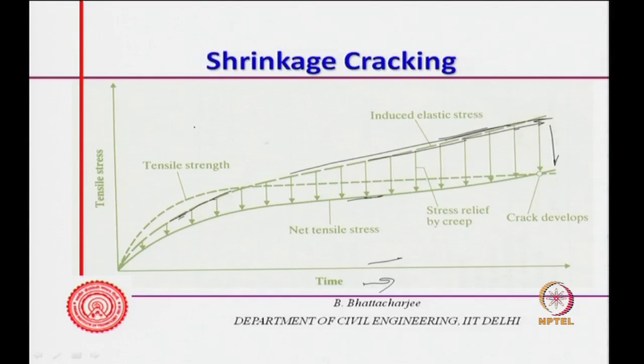So, basically where curing is not proper, this scenario is seen much, particularly in the hot dry desert sort of climate where relative humidity is very little, or in a composite monsoon climate during the hot dry desert season. Shrinkage will increase with time, tensile strength also increases with time, but since it is sustained and restrained, there will be some relaxation.